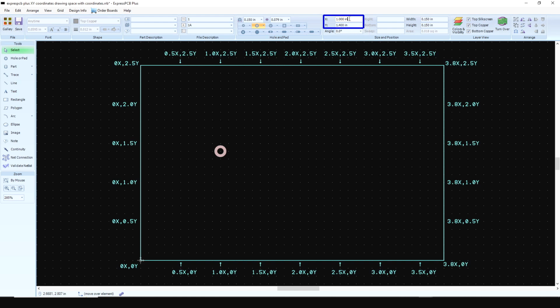And I'm going to left click in there. And you'll see that I now have that little flashing bar. And I am going to change that to 1.9 inches. And the easiest way to do this that I have found, now I can do it this way. I can hold down the left mouse button, swipe it like that. I can move it with the arrow keys like that. But the easiest thing I found is just click in there, do a Control A. That highlights the whole thing. Type in 1.9. Now I'm going to move down to the Y box, but watch what happens to the pad when I click in the Y box.